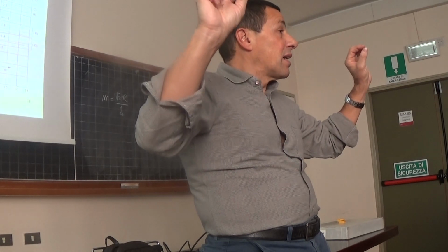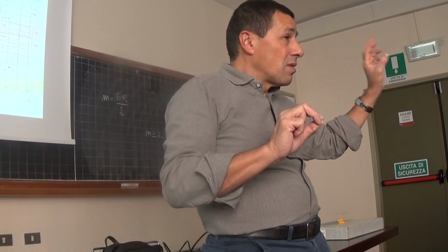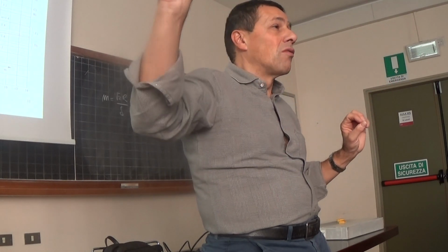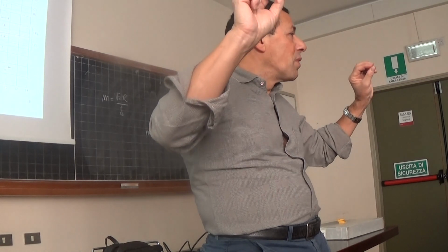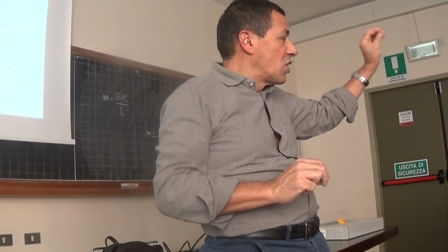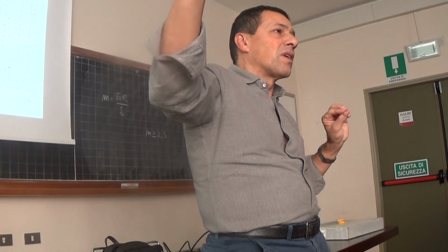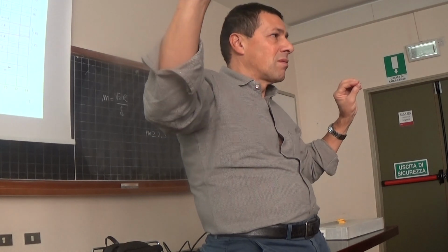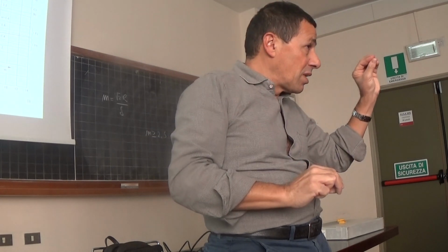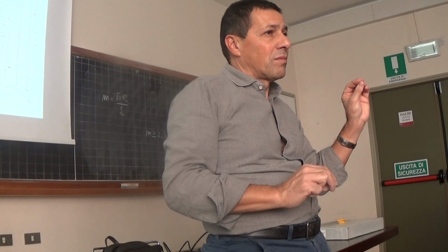What does it mean? That the variation of resistivity is much less important than the variation of permeability. There is not a proper compensation of the variation of permeability with the variation of resistivity. The driving parameter is the magnetic permeability. Okay?